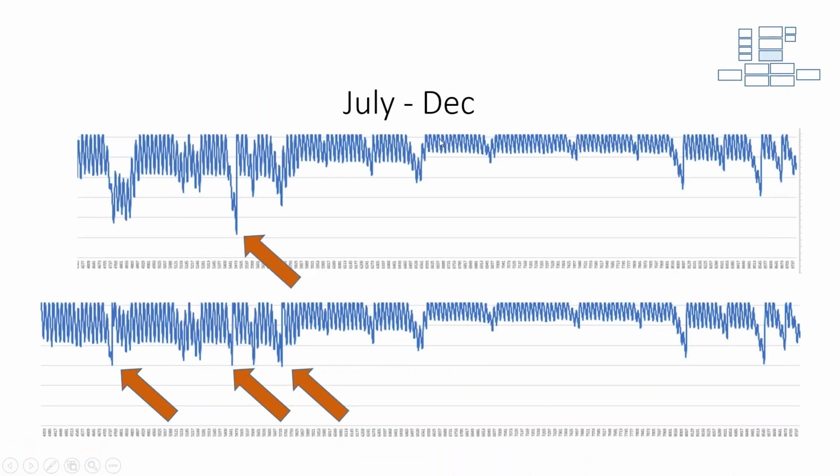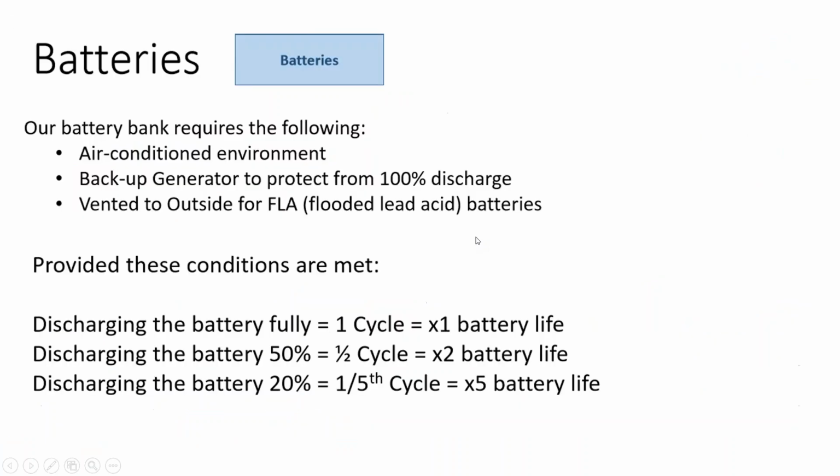This is us taking our PV watts data, our battery bank guess, and pegging it at the 80% depth of discharge and having it charge all the way back up. Now, because it's flooded lead acid, we needed the room to be ventilated. If you're using AGM or gel, they're more susceptible to temperature change than flooded lead acid. Being able to off-gas the battery gives it longer life, better conditioning.